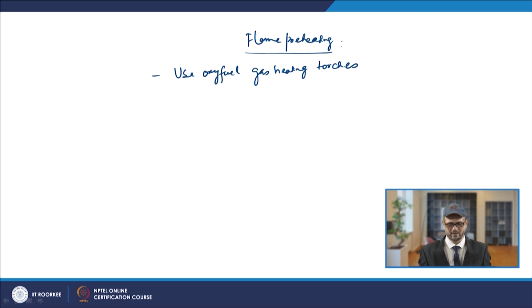You can control various flame sizes, and multi-flame heating heads will be there in those torches. You will use smaller tips for light heating, and larger tips for heavy heating. So, that way you use the torches.